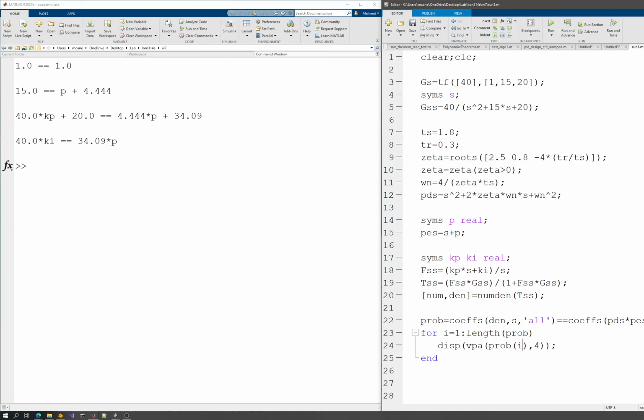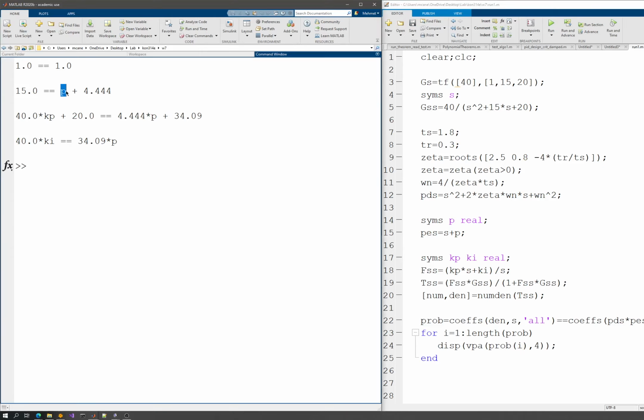There we go. Now I can directly evaluate the value of p. It's 10.66 or something like that, maybe 556, I don't know, yeah, you get the idea. I can approximate the value of p. Since I know p, I can multiply this and see what ki should be, and then I know ki, so I know again p, so this gives me the value, extract 20 from it, and you will get kp. So even without MATLAB, it's pretty much easier to look and solve.